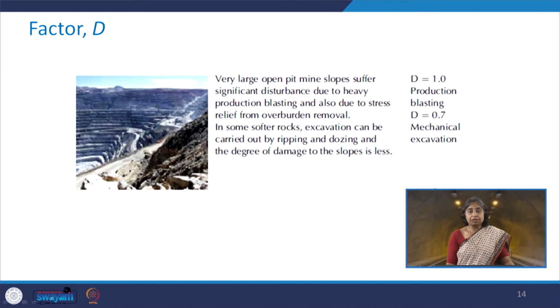And finally, if you have very large open pit mine slopes which suffer significant disturbance due to heavy production blasting, then one needs to go for the value of D as 1, and if you have mechanical excavation, then you can reduce this disturbance factor to 0.7.